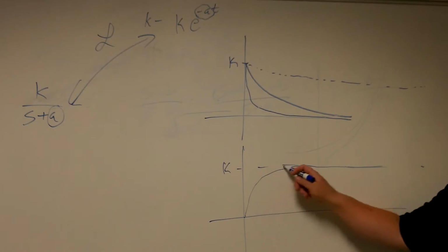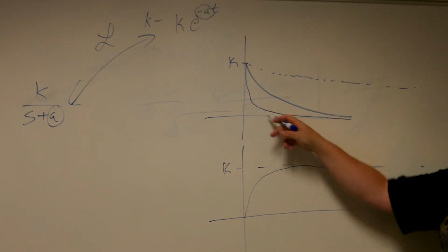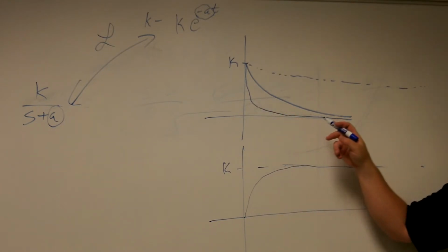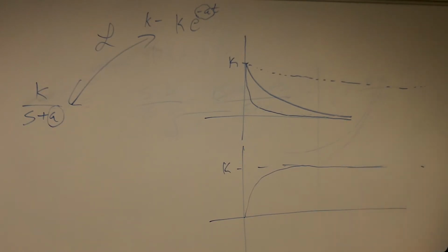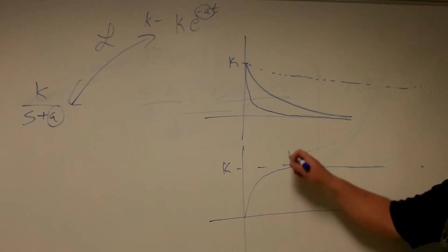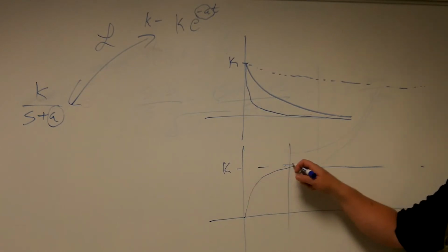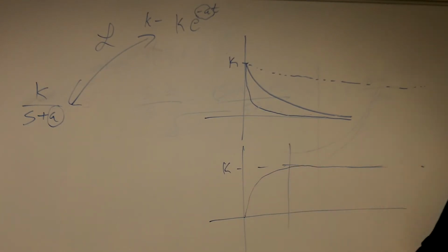We call these the transients. So this is the transient part of your signal that's going on, and then this is your final value. That's where it's asymptotically going to. When you go for engineers, you typically have a period of time when your system's kind of warming up or initially responding to something. We say until the transients die down. We're just saying until this portion gets small enough that it's close enough to there that it's good. And that's usually defined as some percentage.